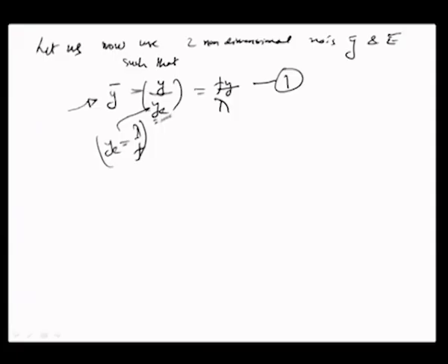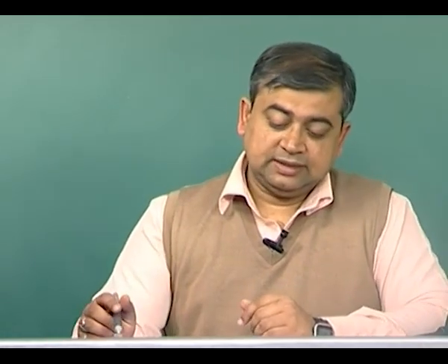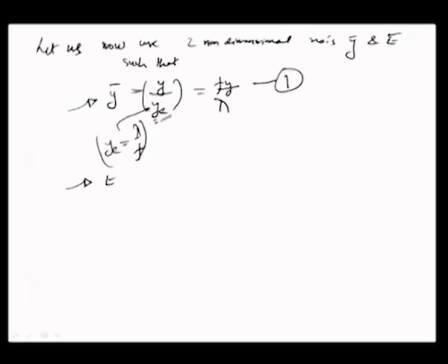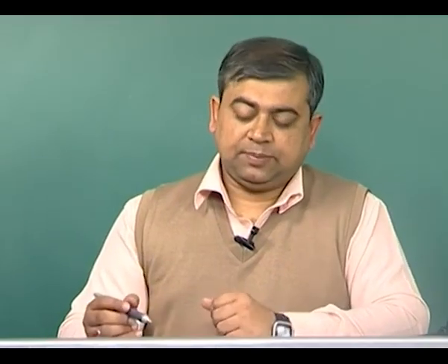At any particular range of operation, it is the scale which varies and the ratios remain the same, and the final equation which will result will be in terms of ratios of those scales. The other thing is the time ratio t dash, which is represented by the actual time divided by the time that is needed to cover up this equilibrium gap, assuming that the tool is moving at a feed rate of f with respect to the workpiece.